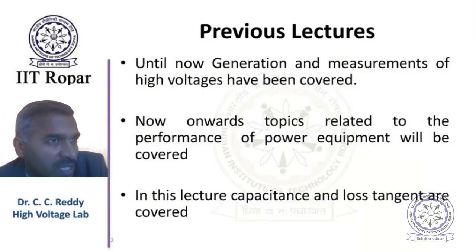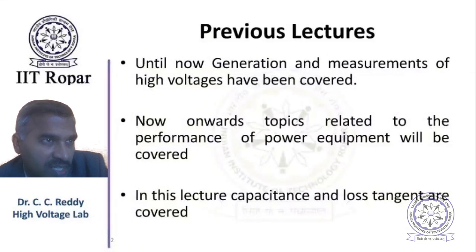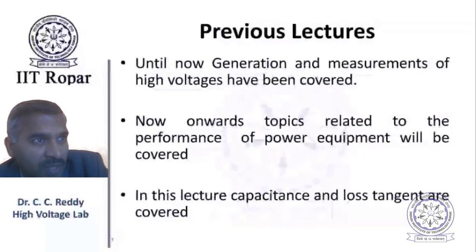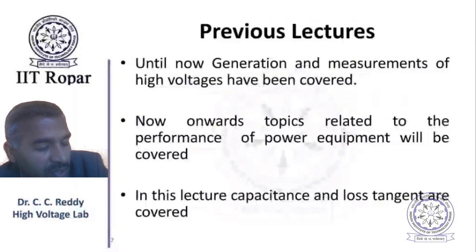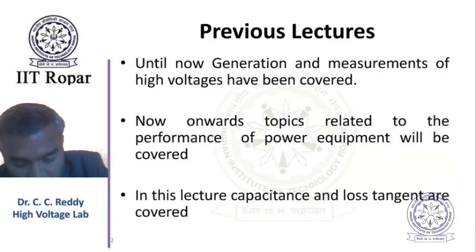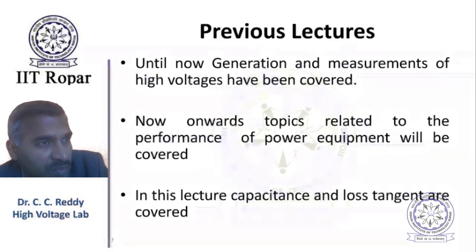For example, in a rotating machine, the stator core is at ground potential, the stator winding is at live potential, and in between there will be insulation like varnish and Teflon or other materials, even paper or cloth can also be used. Even in the transformer, the same thing.